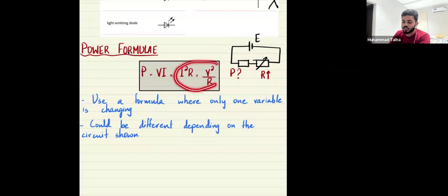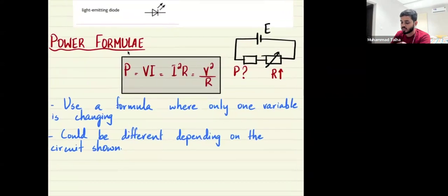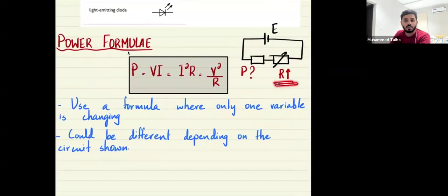I should now turn my attention to these, and I'll show you how both of these will give me the same conclusion. If the resistance of the rheostat, the variable resistor, goes up, total current would go down. And because P through this is I squared R, the current goes down, so power also goes down. Another reasoning is this, that if I think about voltages here, as you were just looking at the voltage division, because this resistance goes up, this resistance will now take up a larger share of the voltage, so the voltage across here goes down. So if voltage goes down, power also goes down.